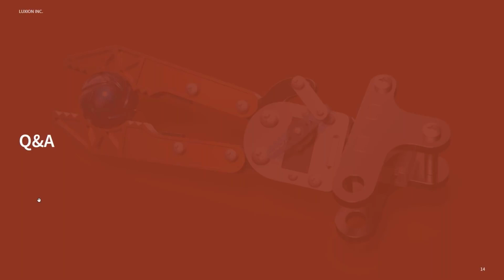So there's actually a function within the import dialog of the native SolidWorks import that allows you to automatically assign materials from the library. Yeah, it would reference the appearance names in SolidWorks and those in KeyShot and try to match them up. But that does require you to use the direct importer. It's certainly something we can look into adding to the plugin.